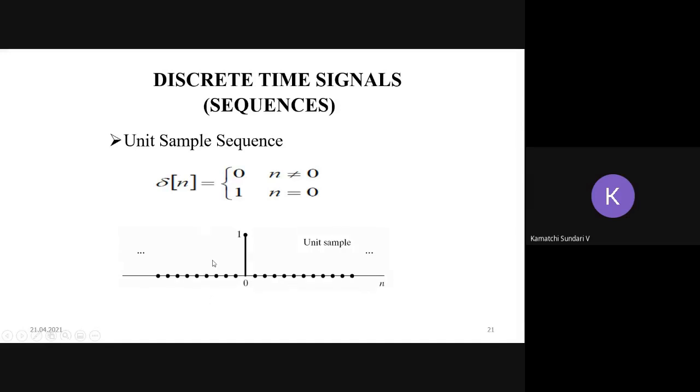So if you want to represent it with the signal, right, so del of n is equal to, you can write it with the square bracket also. So instead of writing this kind of equation, we can represent the sample values. Del of n is equal to, with the square bracket, 3 dots, and then 0, 0, 1, 0, 0 and 3 dots. You have to close your bracket, either within the braces or with the square brackets you can write, right? So either the samples can be separated by comma or separated by space.